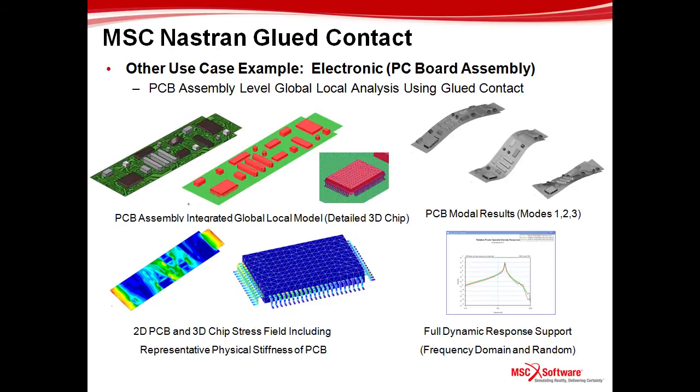This is an example showing where we have glued the 3D chip to its leads and the leads to the PC board, which is actually a shell component here. And because glued contact is established right at the start, then you can push this into frequency response and perform modal analysis, or random in this case.